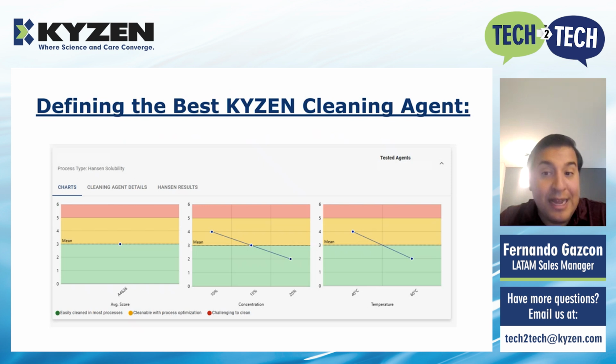Once all residues were identified, and given the fact that they were using a spray-in-air inline, we recommended an AQUANOX cleaning product, a water-based cleaning agent capable of removing all identified residues, providing a safe and reliable cleaning solution. KYZEN has a massive database of flux residues with which we have previously run cleaning trials. With this historical information, we were able to provide a baseline of parameters to start testing when working with a new customer and application like this one.